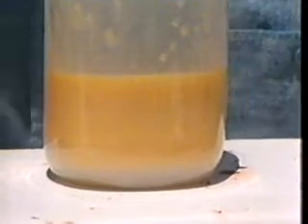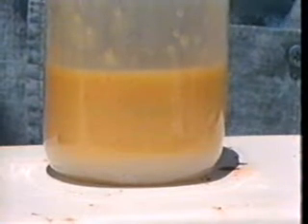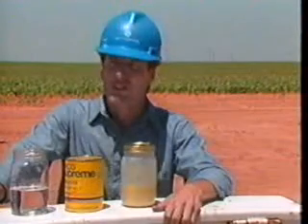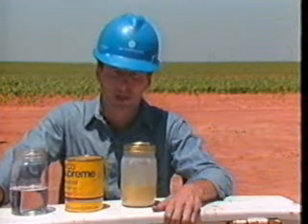The settling rate is also affected by the size of water droplets. Smaller droplets are lighter and take longer to separate through settling. If the difference in API gravity between water and oil is small, then separation is slow. However, water weighs more than oil and will eventually settle to the bottom of a vessel.